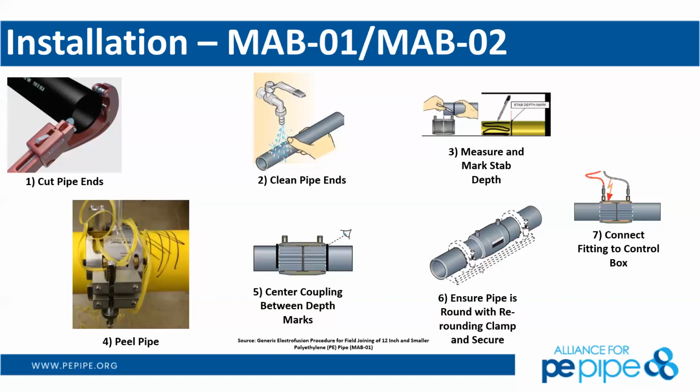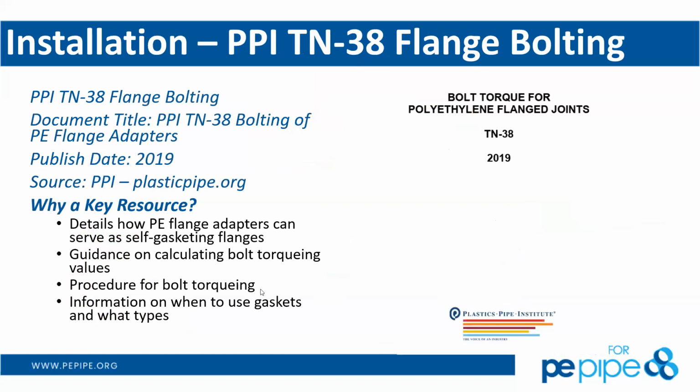So it sounds like there's just a few more steps in an operator process for electrofusion than in the butt fusion process. But in small diameter, those service connections actually are much easier to fit into those areas as opposed to a full butt fusion machine. Correct. So that's a true benefit of it as well. For repairs or in-ditch connections, electrofusion can be really good. You use a lot smaller machine. It's much easier to do, though there are in-ditch butt fusion machines as well. So absolutely. Thank you very much, Rusty.